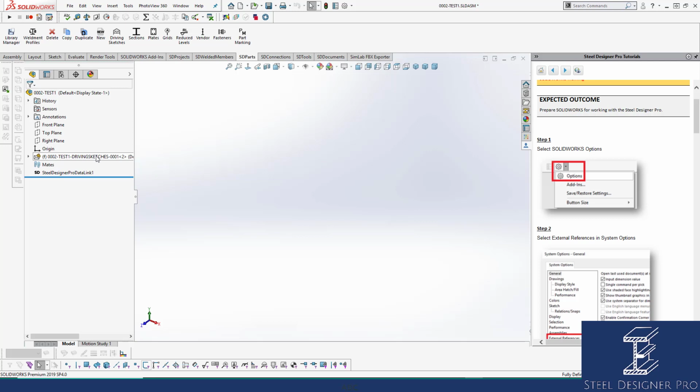There's nothing inside of it, and you'll notice because I've deleted the first instance of driving sketch 1, it's now jumped to driving sketch 2 automatically, even though 1 was in there before. If I wanted to reset that instance, I'd just get out of the assembly, get back in the assembly, and then insert the new item, and then that'll kick off as 1.